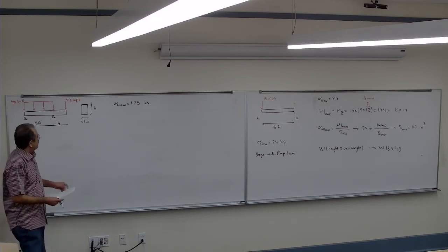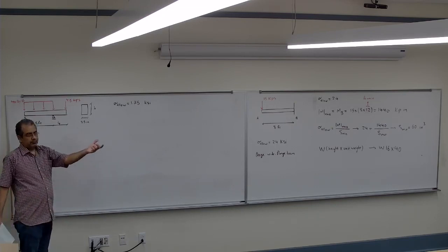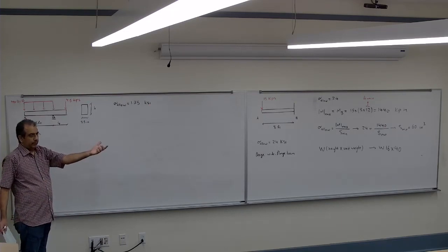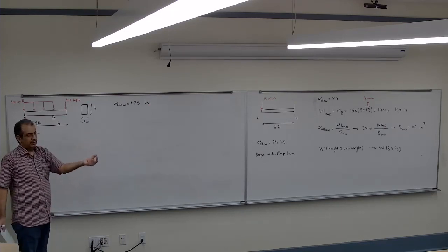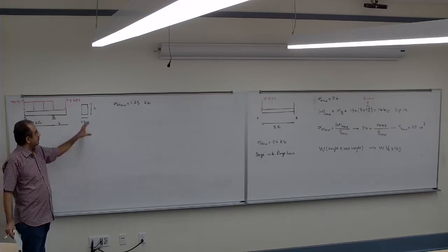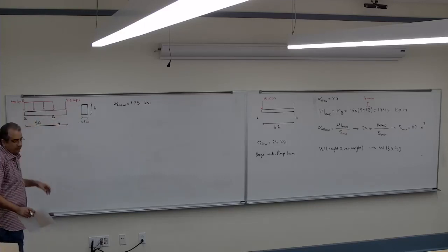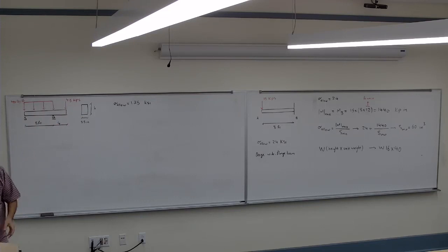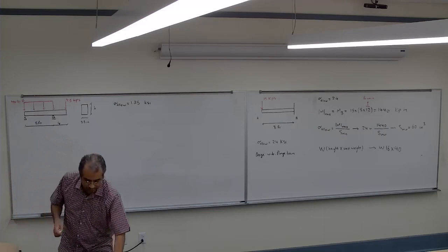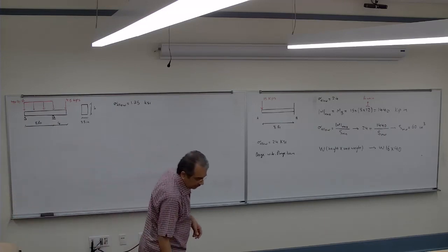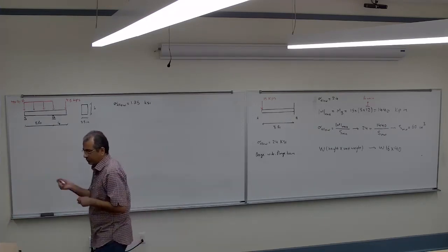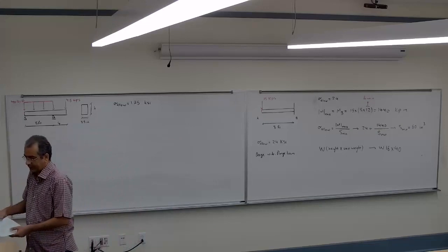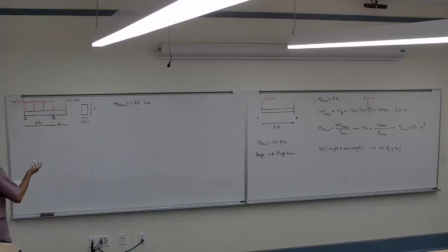So basically the situation is that the shop will go to buy a timber, that's a 4-inch timber. And say, okay, what would the height I need to make sure that it's gonna support that. So the very first step is that I have to draw the shear and moment diagram. To do that, I need to find the reaction of the support. I'm not gonna do it, I'll just put the numbers there, but you have to calculate them basically if you want.